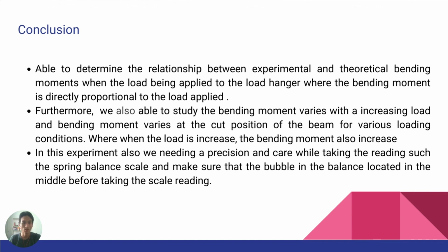Lastly, in this experiment, we also need precision and care while taking readings. We need to make sure that our eyes are in a perpendicular position when taking measurements on the spring balance scale, and also make sure that the bubble in the balance is located in the middle before taking the reading.